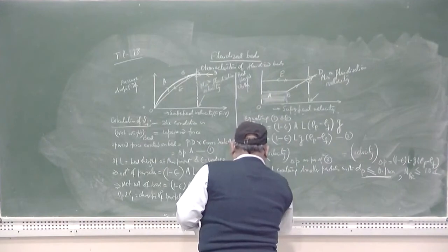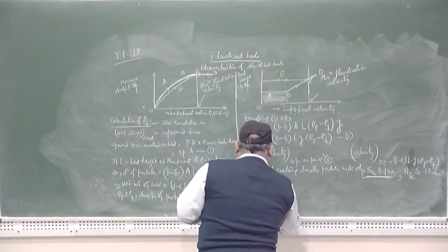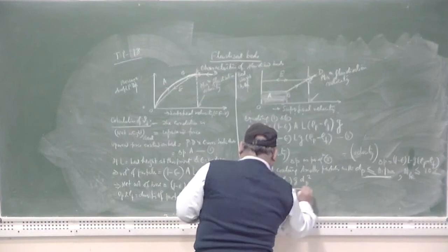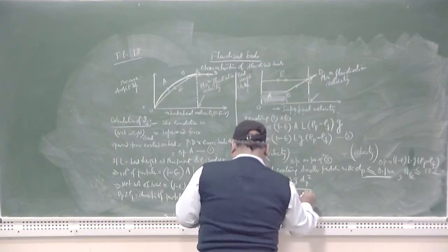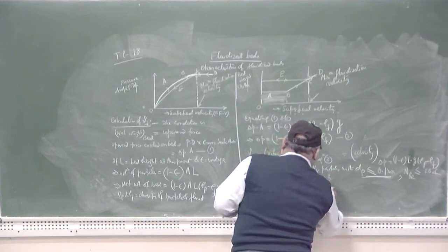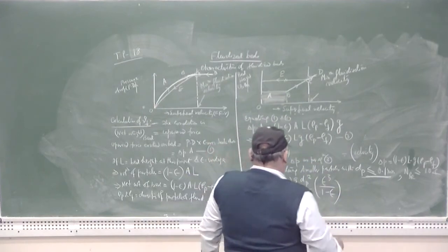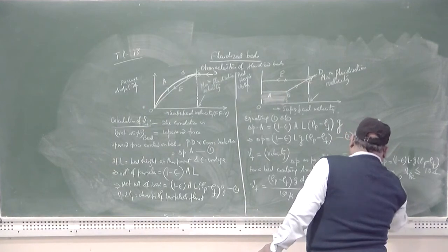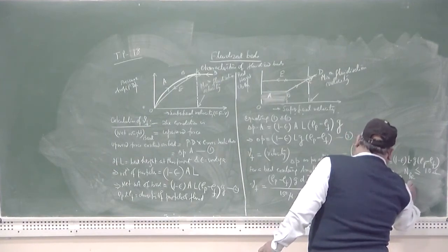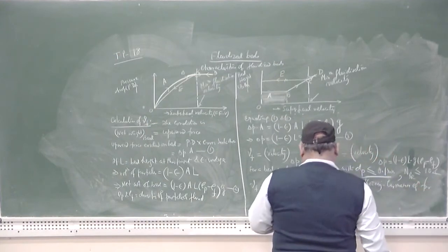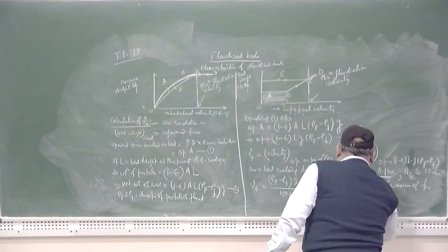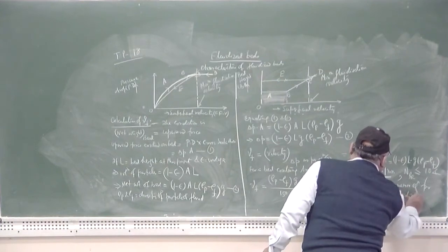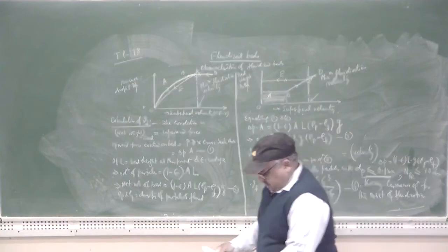Vf is given as Vf equal to (rho P minus rho F) into g into dP square divided by 150 mu, into epsilon cube divided by (1 minus epsilon). This is equation number 4. This is called the Kozeny-Carman equation for the onset of fluidization.